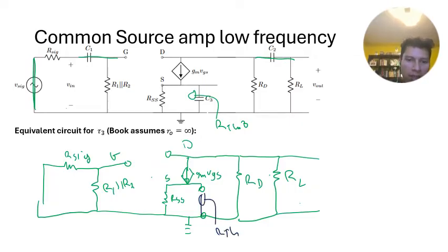So we're going to stick a Vx here. Let me just redraw this. We're going to stick our Vx here, plus minus Vx. And whenever you have a dependent source, I don't know if you've already noticed this, the first thing I do is try to write VGS in terms of Vin and Vout, or between any kind of source in our circuit.